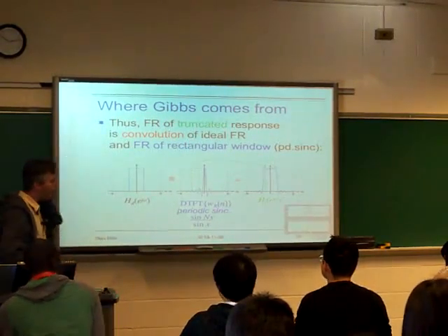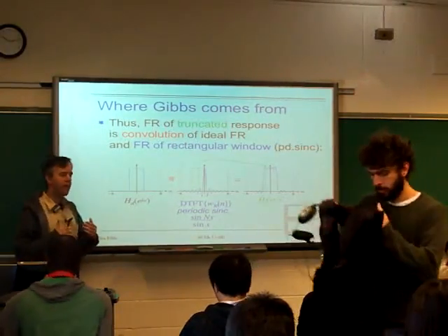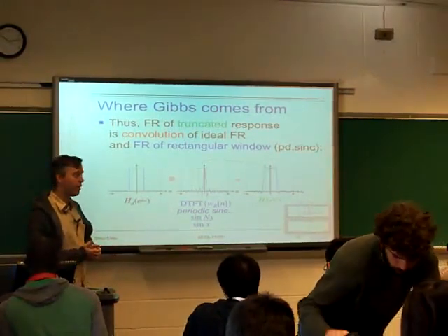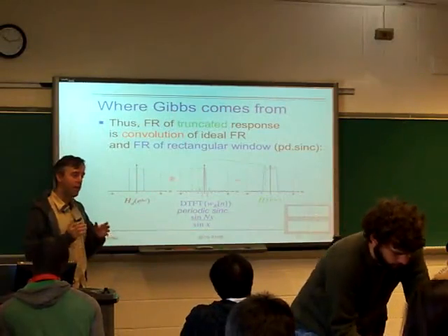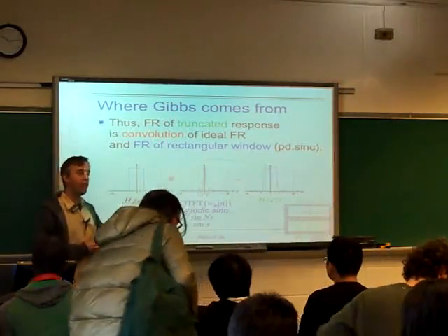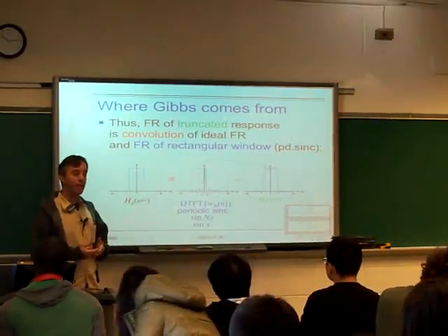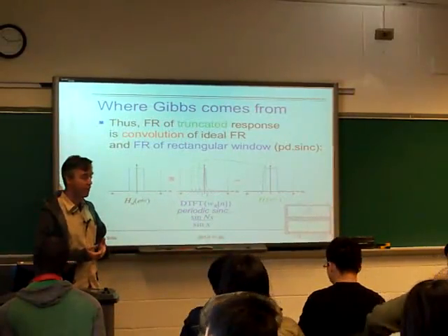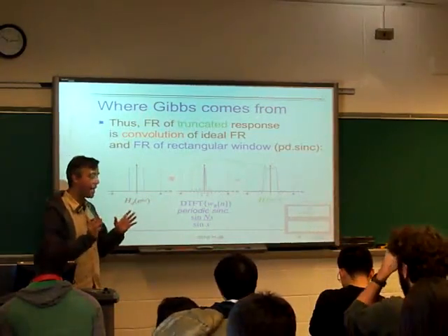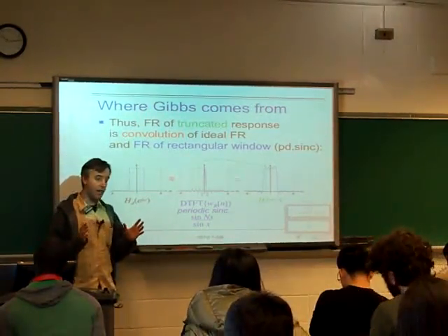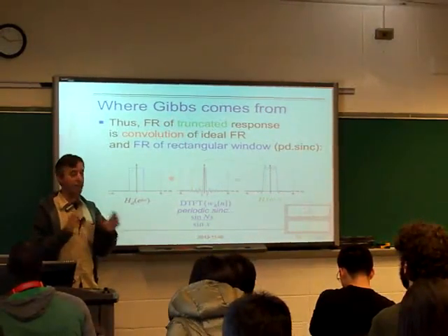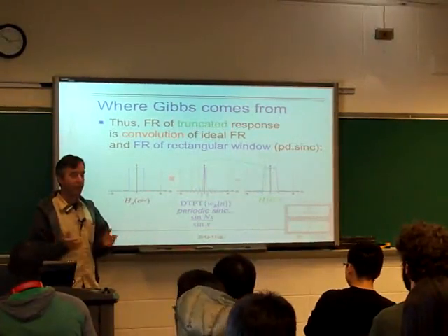Okay, so we were talking about how to design FIR filters. We tried to solve the problem of what is the optimal finite length approximation to an ideal filter. If we define optimal in the sense of minimum squared error, integral squared error in the frequency response, then we find that the best filter we can do is just to copy the ideal impulse response, the inverse DTFT of the ideal frequency response, over the range of samples that we've got, however long a filter we can have.